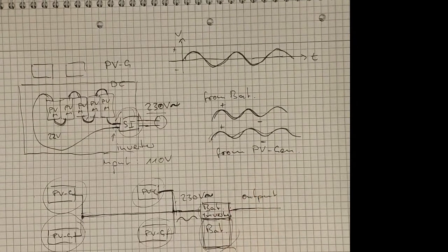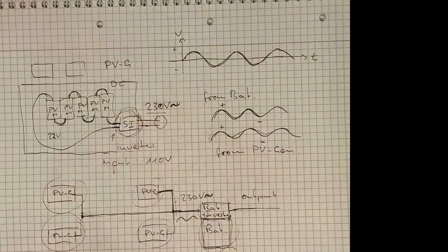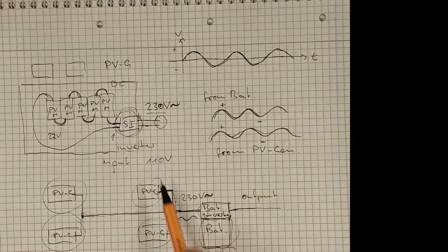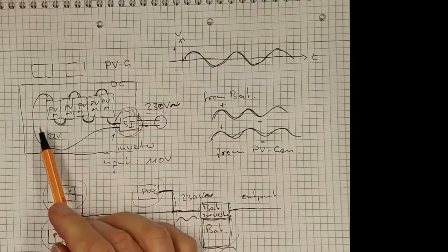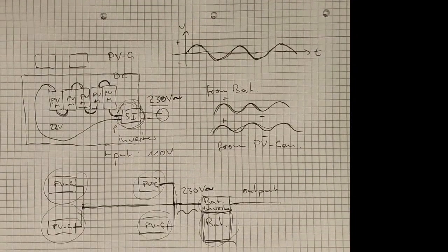So this is how it works, and therefore you need high voltage for these photovoltaic generators. The higher the voltage on the input side, the better the efficiency of this solar inverter is. When you connect them in parallel, you are increasing the current, but you are not increasing the voltage. But you have to increase the voltage. That is the reason. That's a good question. Yeah, okay, I think that's it basically, right? That's what I wanted to discuss with you.